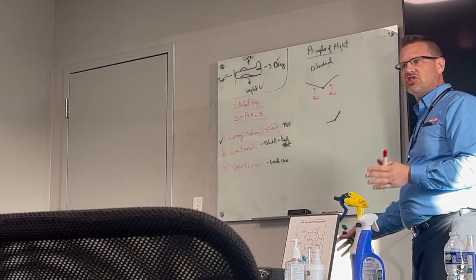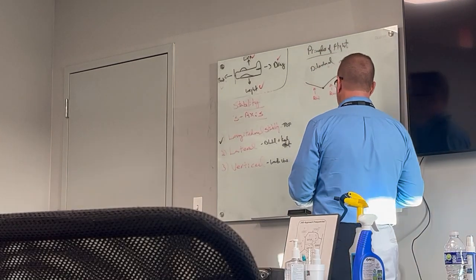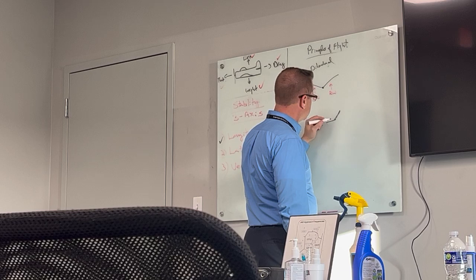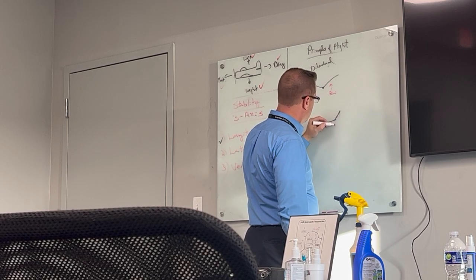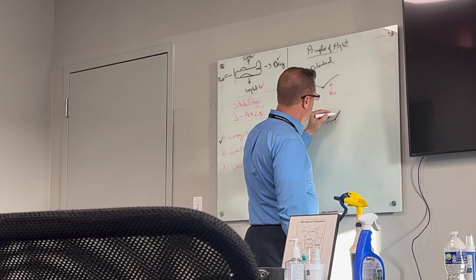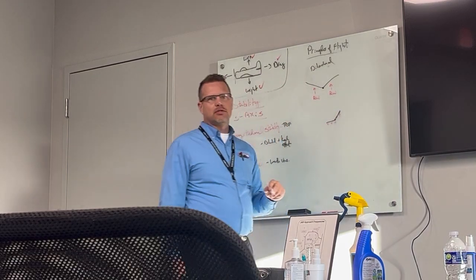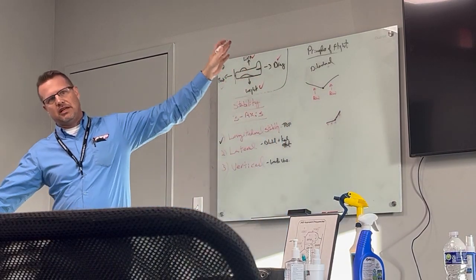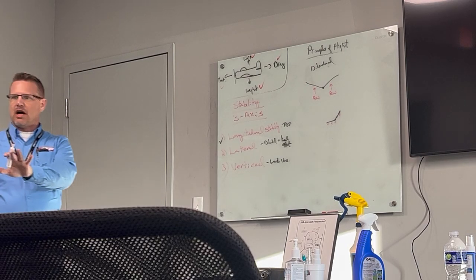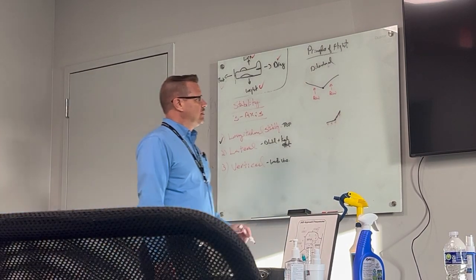It's going to slide off, or slip off. And so when that happens, our relative wind is no longer coming directly at the plane. It's still coming at the plane, but now it's coming from the side angle because the plane is now slipping and moving forward at the same time, okay?